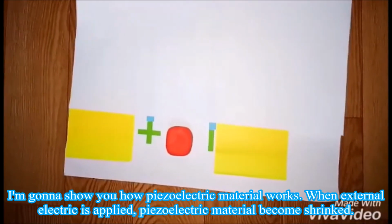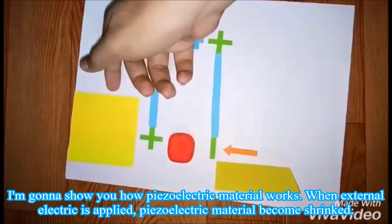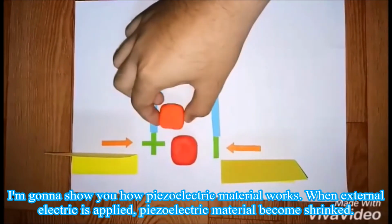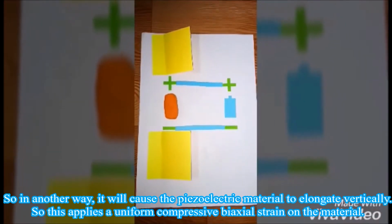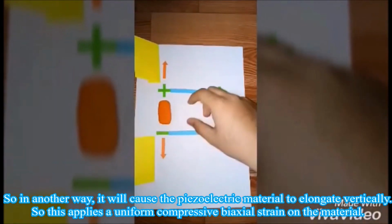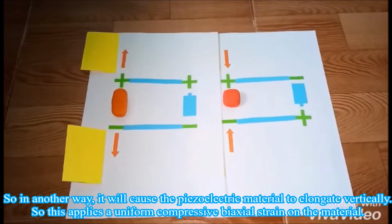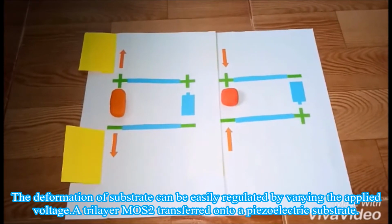When an external electric field is applied, piezoelectric materials shrink. In the other direction, it will cause the piezoelectric materials to elongate vertically. So this applies a uniform compressive biaxial strain on the material. The deformation of the substrate can be easily regulated by varying the applied voltage.